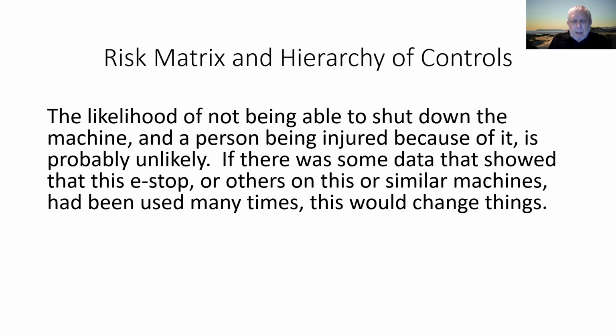The likelihood of not being able to shut down the machine and the person being injured because of it is probably unlikely. If there was some data that showed that this e-stop or others on this or similar machines have been used many times, this would change things. E-stops usually don't get used very often, and that's why when something's missing like that, sometimes it goes unnoticed. If you have data that shows anything different, you could change this. But the likelihood is probably unlikely.